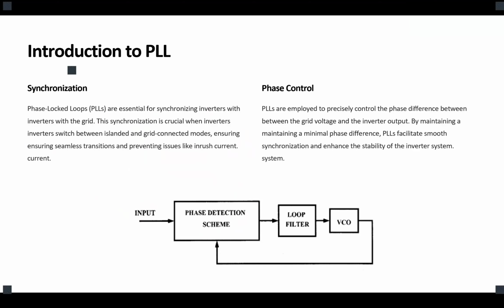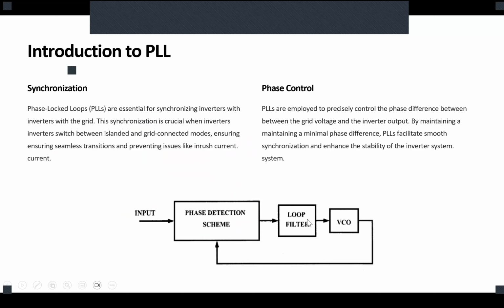And we said this PLL would have three main components in order to measure the frequency of the grid and try to eliminate the difference between the already existing settings in the control system and the measured frequency at each time. That means because it tries to mitigate the error again, the PLL has a kind of PID control aspect within it.